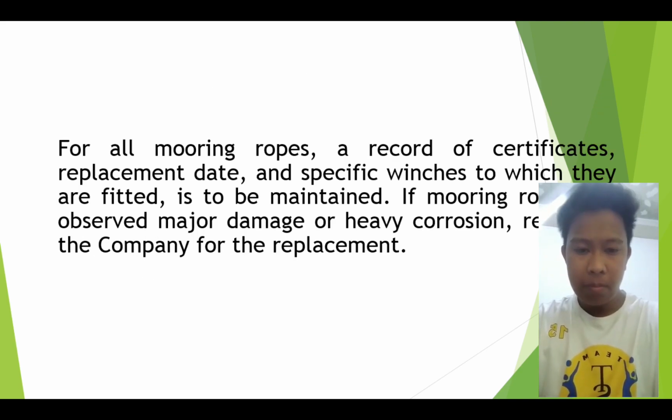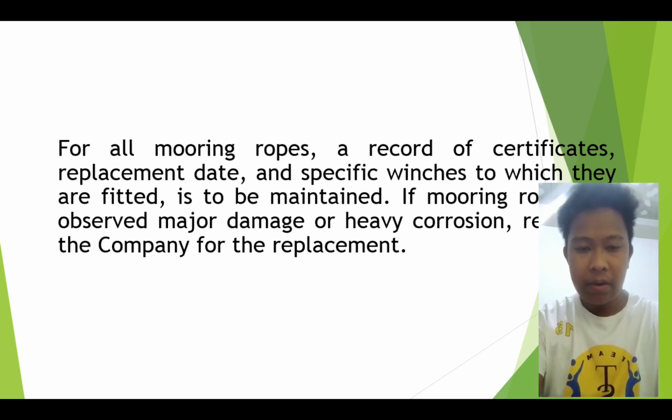For all mooring ropes, a record of certificates, replacement date, and specific winches to which they are fitted is to be maintained. If mooring ropes are observed with major damage or heavy corrosion, report to the company for replacement.